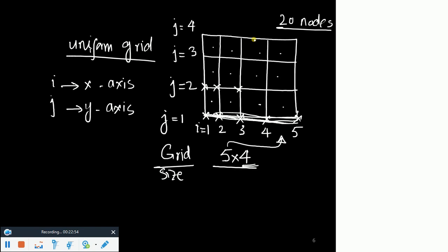Now, what's the point in there? It is a Laplace equation, second order in x, second order in y. So you need to have 4 boundary conditions. So you know the temperature at this surface, you know the temperature over there, you know the temperature over there, and then over there as well. So even if you go for the computation of temperature at the nodes, how many unknown nodes would be there? Come on, all the nodes on the boundaries, you know the values. 1, 2, 3, 4, 5, 6.